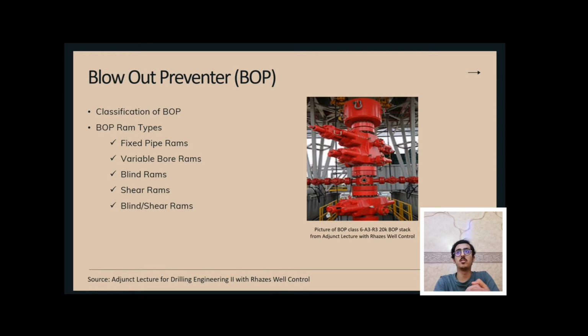Blowout preventer, or BOP, is a huge piece of equipment which weighs up to 400 tons. Its function is to control and seal the hydrocarbon wells. In other words, it's used to prevent uncontrolled flow of oil and gas due to a kick, which might lead to an event known as a blowout. This blowout preventer may be used in both offshore and onshore rigs.